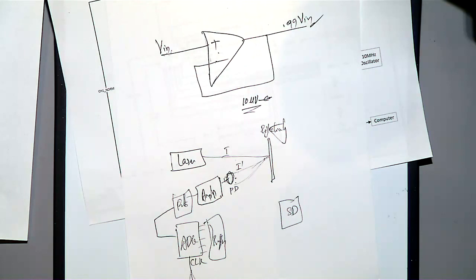I think the ADC clock is much faster than the SPI clock, and the SPI clock should be slower. Yeah, that's fine. All these things, we are just understanding what the blocks required are. Yes, definitely we have to think of the speed when you are drawing the circuit, but this is only the system level, what each block does.